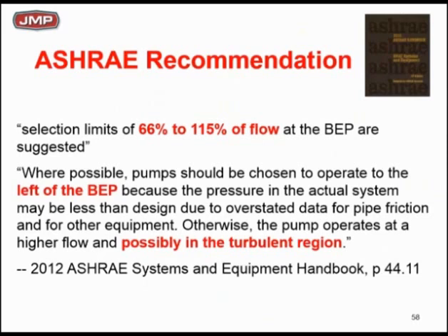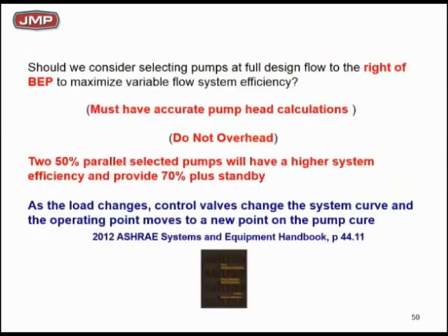If you know your pump head precisely and you're tight on it, you can go to the right of BEP, no big deal. But if you don't know that, or if you're gambling a little bit on it, or you're not sure it's right, or you're not sure it's going to be installed exactly the way you laid it out, then ASHRAE is still telling you to go left of BEP so you don't get in a turbulent area. We'll talk a little bit more about that as we go.